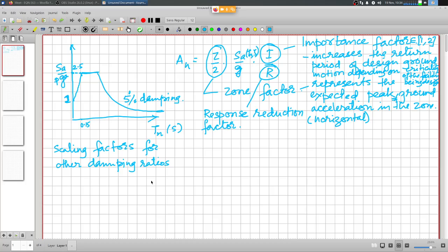So nonlinear dynamic analysis is very tricky and very time consuming, and it's not very reliable either because of various modeling assumptions and various paths that they can take depending on the convergence criteria. Everything might be the same, but two different analysts might use different criteria for convergence of iterations, and that may change the response trajectory completely.